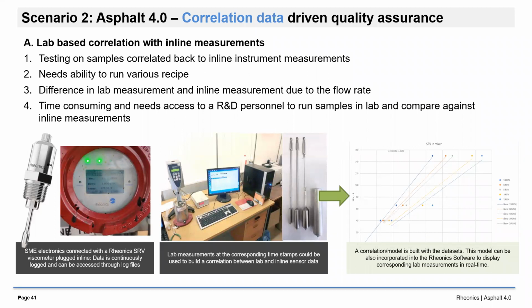And the SRV sensor, which is in that terminal while that asphalt is flowing across it, gives you a value of 260 centipoise at a temperature in excess of perhaps 200 Fahrenheit, right? Completely different temperatures. Now, by using the model which is available on the sensor, you can convert the value being output by the sensor, the line viscosity, into a lab equivalent viscosity. So what is the benefit of that?